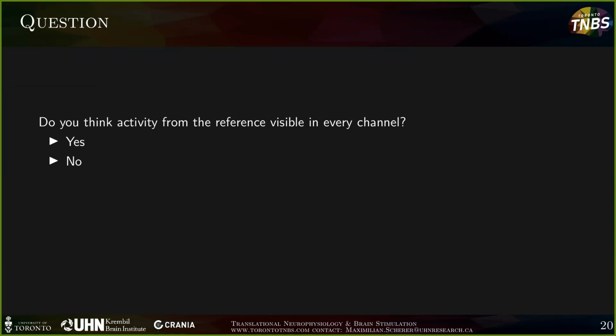So basically, 33% of you said that the activity from the reference is going to be visible in every channel, and 2/3 of you said no. And the answer is basically that you should never trust that Ask the Audience joke on the Who Wants to Be a Millionaire show, because you see it in every channel. Whatever happens in your reference is going to be visible in every channel you're going to record, because you're measuring the gradient between a site of interest and that reference. So whatever happens at the reference gets pushed into whatever you're looking into.